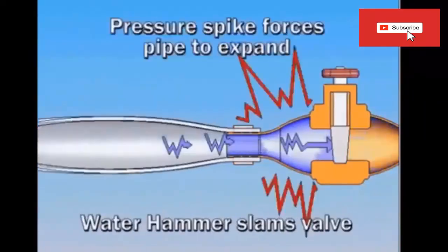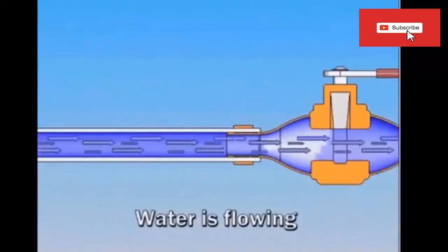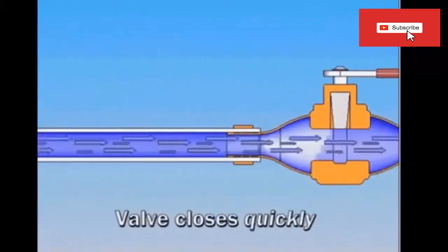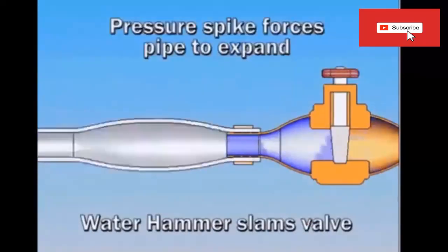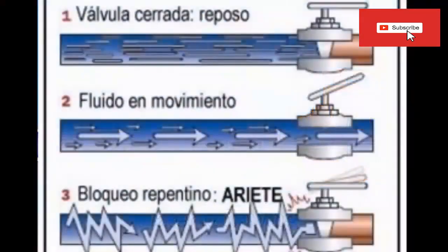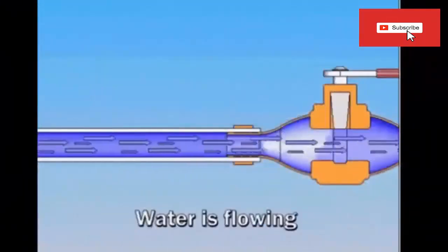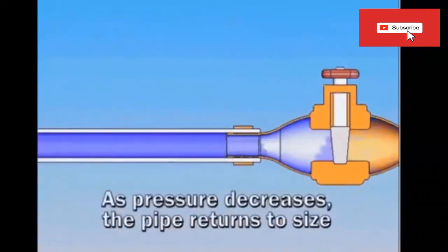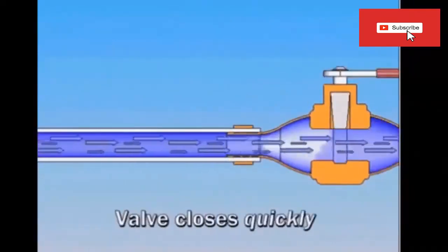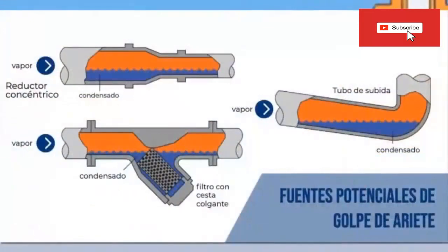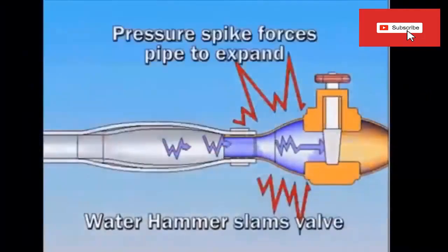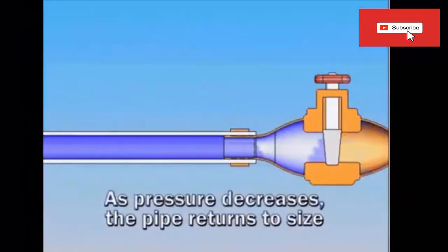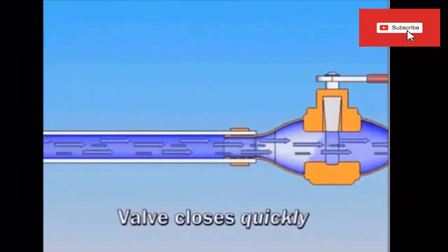These sudden increases in pressure can damage valves, taps and other equipment, even causing bursts in the pipes. It is known as water hammer, due to the sound that can be produced, similar to hitting the pipe with a blunt object such as a hammer. Water hammer does not occur only if we open or close a shut-off valve abruptly, but it can also happen when the pump is started and stopped. A direct start or stop can suddenly set a large column of water moving through the pipes, and can produce this effect.